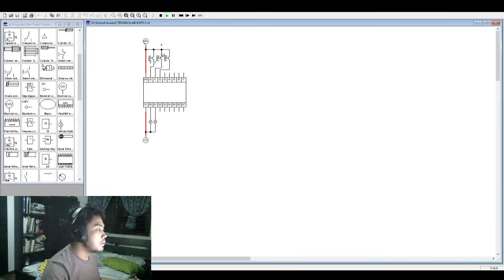If we press PB2, we can see that lamp B is the one turned on, and if we release PB2, it is still turned on. And since PB2 is the first switch that we pressed, when we press PB1, nothing happens. So it satisfies the first two conditions, and again, if we press PB3, it resets the system.